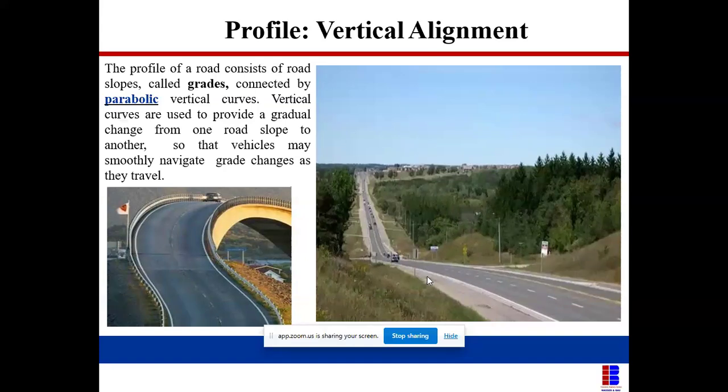If I'm climbing a hill, driving on a crest vertical curve, and I design that road for 60 km per hour, and I'm not seeing a vehicle coming, and I want to overtake, this K value is what we use. If the K value meets the required criteria, and I'm using the required speed for that particular road, and that person coming is using 60, me coming using 60, we will not collide even though we're not seeing ourselves. There's a way we can navigate each other without colliding.